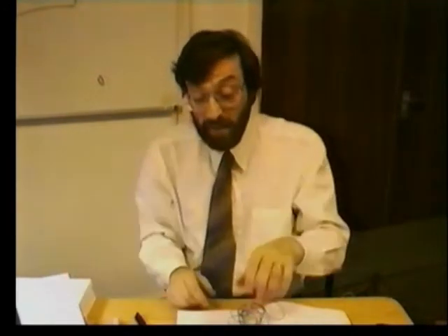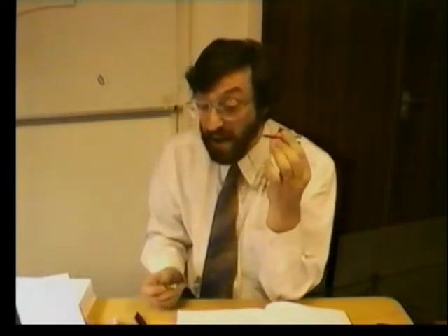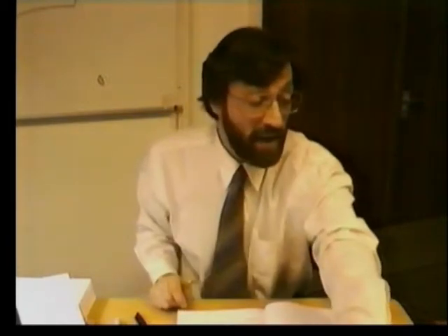Very simple concept. You can take a balloon, blow up the balloon, and the more the pressure, the bigger the balloon, because the balloon is converting pressure into linear displacement. If you do that with an enormous thick piece of steel, the rules are still the same. This is a bellows, but it measures extremely high pressures, and it's used in furnaces and process control. Same concept. We're converting one measurand into another measurand.